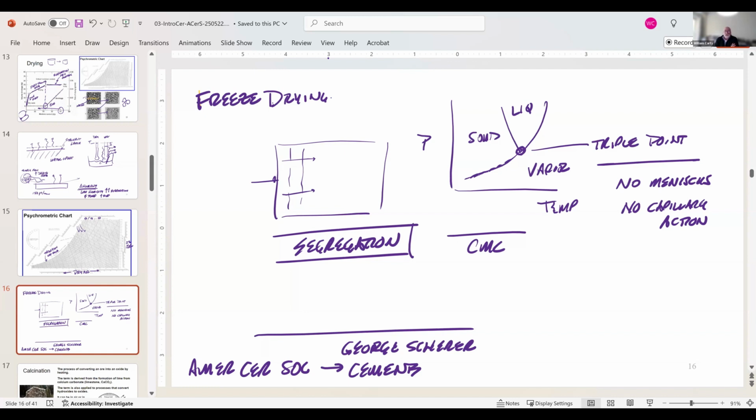They're nucleating ice more efficiently. I would add that to your system to control the nucleation of ice. You're relying right now on a random nucleation event. It could be a heterogeneous nucleation event where the surface is nucleating the ice. But if you were to introduce a chemical that facilitates ice formation, you should get a more uniform nucleation of ice in the system.